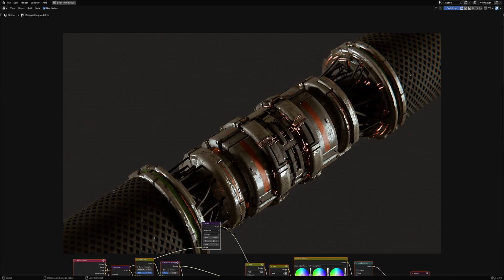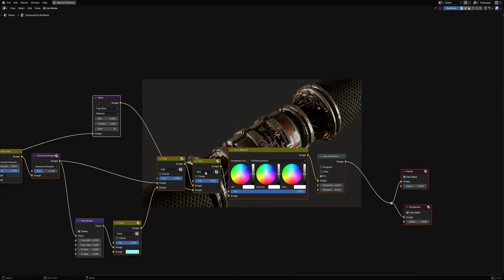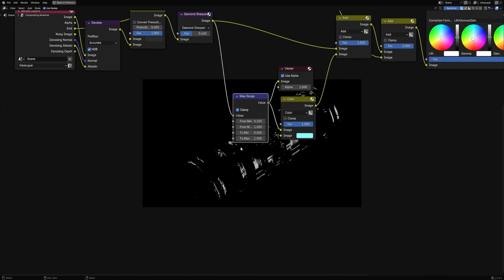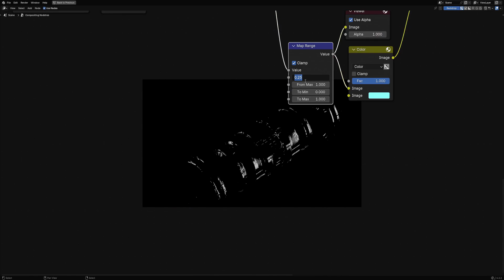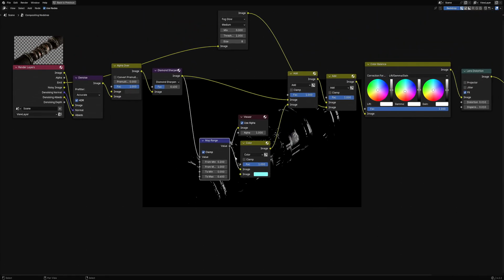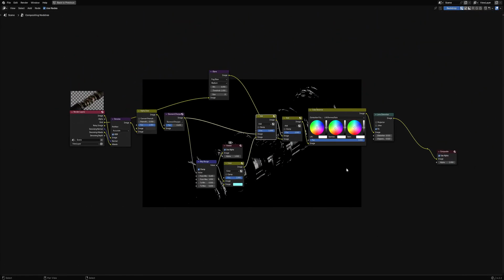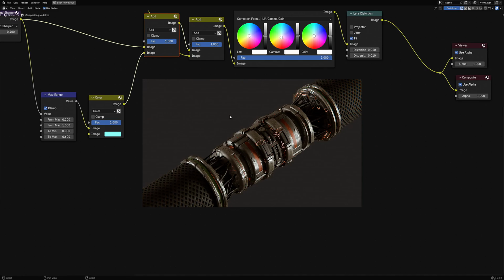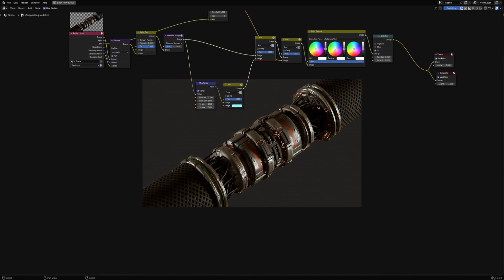and you'll finally see it in the compositor once it's finished. Okay, so this is what we got, and the range, control shift click. Okay, let's use something like 0.2. Going to wait for it to render, and you can make it softer by using a lower bound here. Okay, and it affects the color, this node here. Okay, so it's much softer.